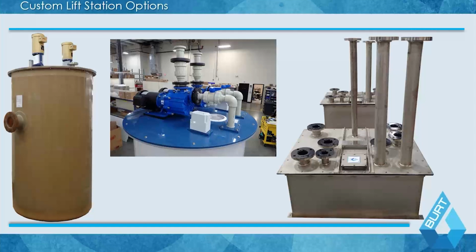A lot of that falls under the fact that while people do make direct bury fiberglass tanks all the time for, say, water or gasoline, they're actually UL tested specifically for that application. Putting a chemical mixture into a tank underground raises a lot of insurance and listing issues, whether or not you can do that and some of the parameters that come into it. So 90% of the time, lift stations are put in vaults or something, and they're accessible as part of their actual design.